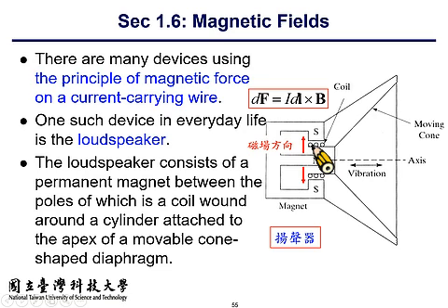And on the bottom half, the current is pointing into the screen, and the magnetic field is pointing downward. So it also produces a force to the left. So the bottom half also pulls the membrane to the left. So it's a consistent force to the left for the top and bottom half.